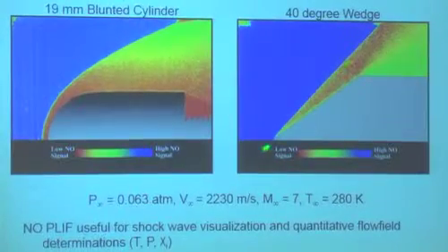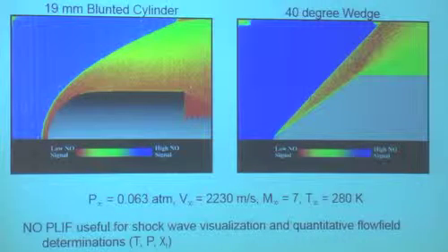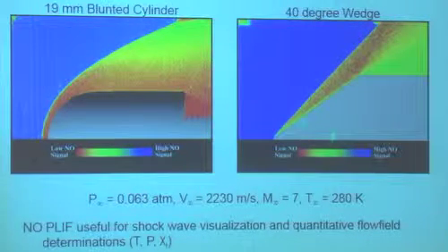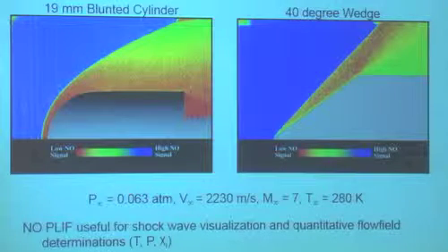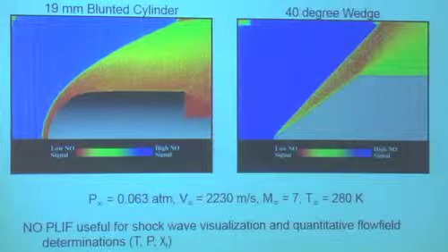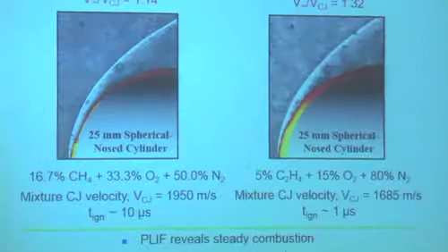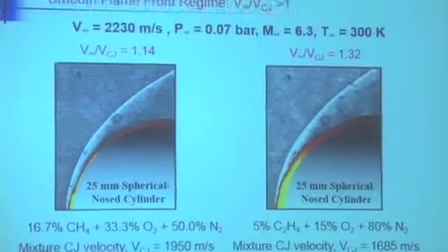Or you can take the flow over a wedge, and we do this in my lab class every year. The flow over a wedge of a given angle, the separation angle, then tells you the Mach number if you know gamma. So this is how you check out your tunnel and make sure that it's behaving the way you want.